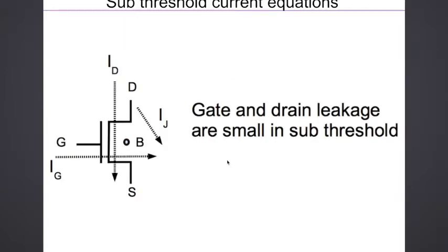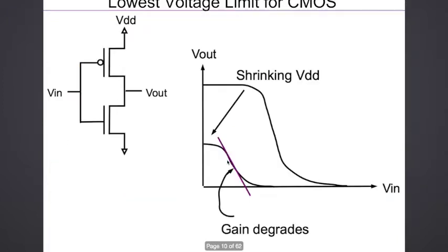Now, so really the problem comes down to having a formula which relates the voltage level to the gain, right? We are talking of the gain at this point. So you have a 45-degree line, you find the gain when the 45-degree line intersects this curve. At that point, you find the gain and relate it to the voltage level. Now, how do you calculate the gain out there, right?